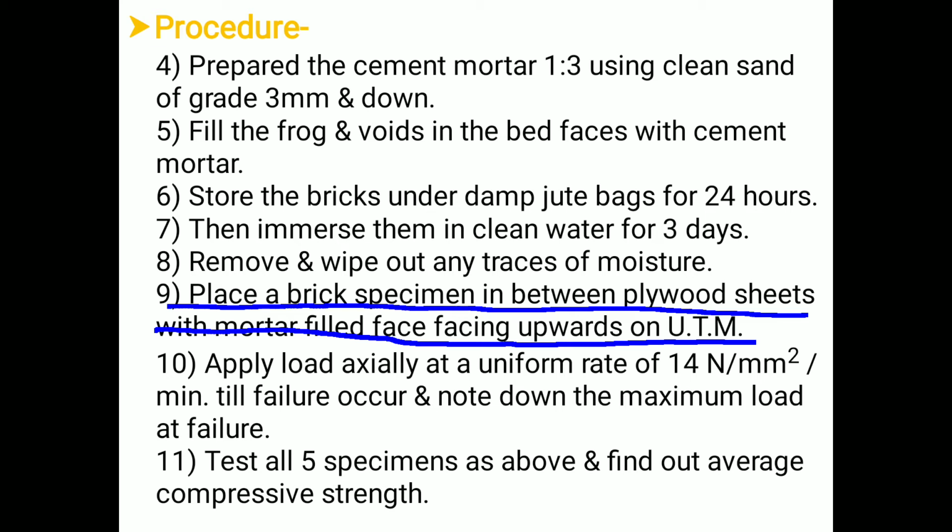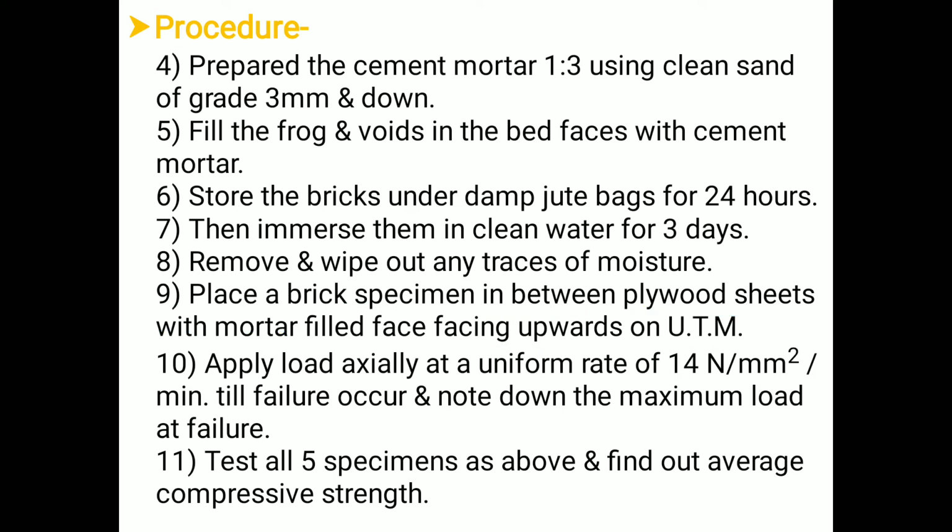After that, we have to apply the load axially at a uniform rate of 14 Newton per mm square per minute. The application of load should be uniform, and we have to apply it till failure occurs.